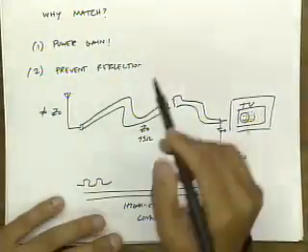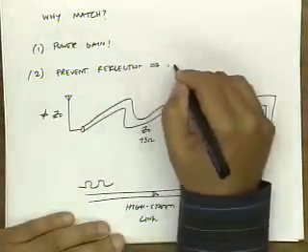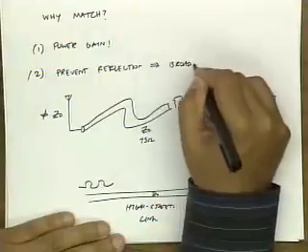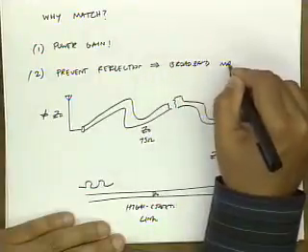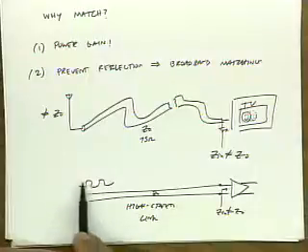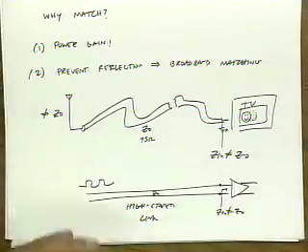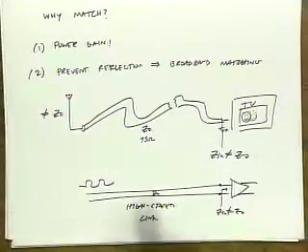And a big difference between case 1 and case 2 is that we really would like broadband matching. In other words, in this case, for instance, this data signal is broadband, it's high speed. So we really would like to provide a termination from DC all the way out to, let's say, a few gigahertz, if this is a gigabit per second kind of link.